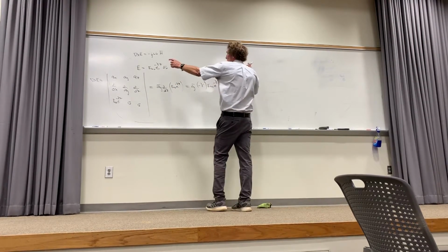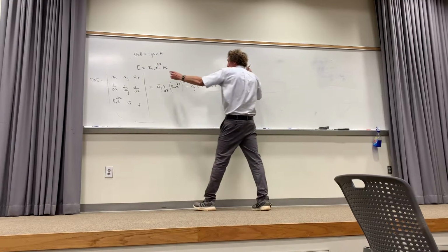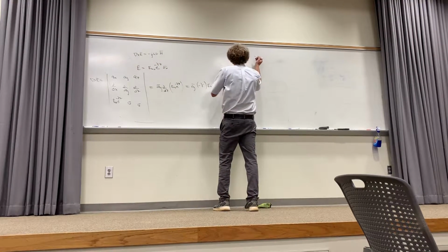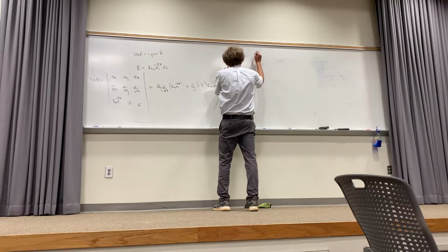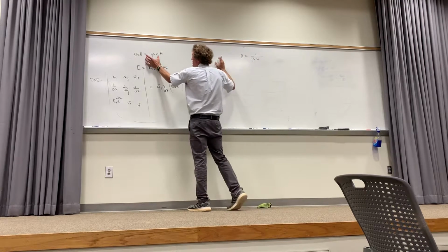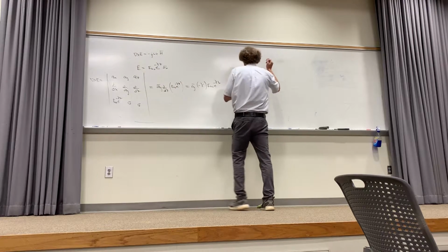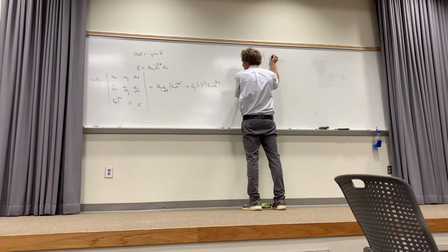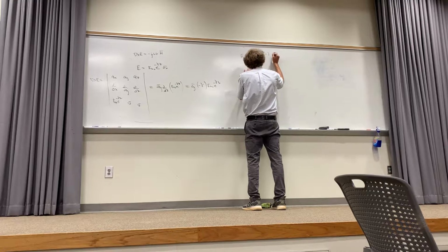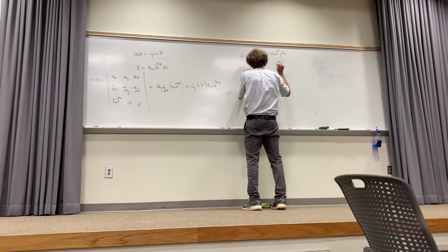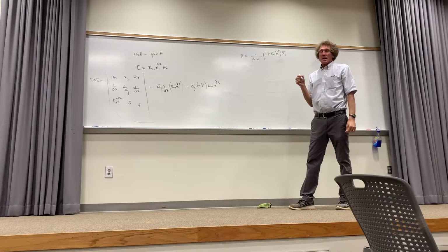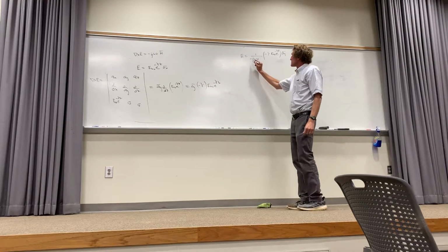So I can say, if I take this equation and I assume that in for that, I get H equals, and I'll put 1 over minus j omega mu. Here I'm taking the minus j omega mu and I'm dividing into the curl of E. Well, the curl of E is minus gamma times EX0 times e to the minus gamma z in the AY direction. You all see that, class? And what do you see happening? The minus signs cancel, for starters, right?